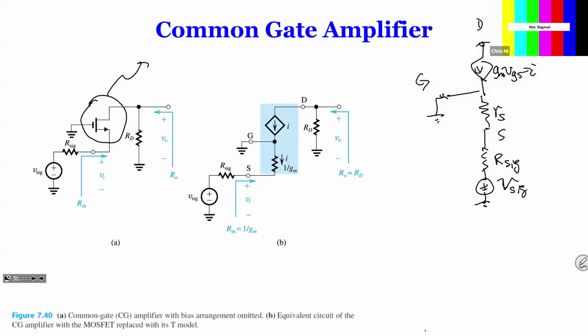So the next we're going to look at the drain. It's very simple. In this case, the drain only has RD connected. So we're going to connect this drain RD to ground. And sometimes you also have a RL connected as the output. But that's not going to change too much because when you have RL connected, RL and RD are going to be in parallel. And sometimes we also have RO, which is early resistance. And when you have that, all three resistances become in parallel. So it doesn't change the whole picture. Only the value actually changes a little bit, our load resistance.